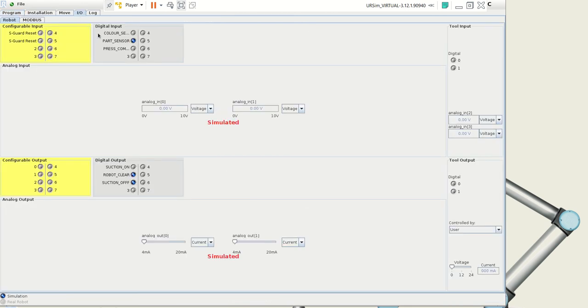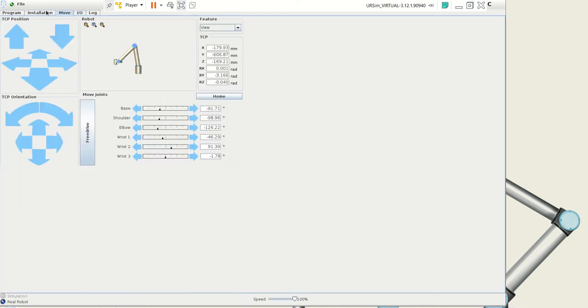So what I need to do is, I actually have an output, okay? So you can get two sensors, transmitter and receiver, okay? And basically, if you set one sensor on the robot, so you attach to the robot, and then the other sensor onto the machinery that would be linked into the PLC, or the other set of machinery, that's the controller that's looking after that. So you'll see I've got a digital output that I've set high. That's basically just said the robot is clear, okay?